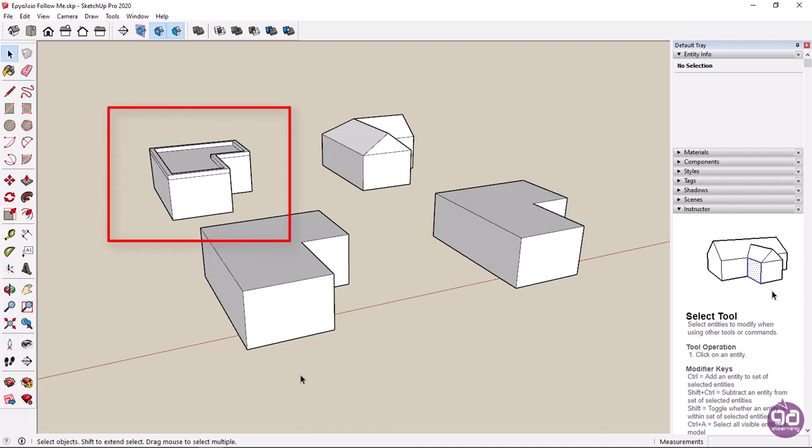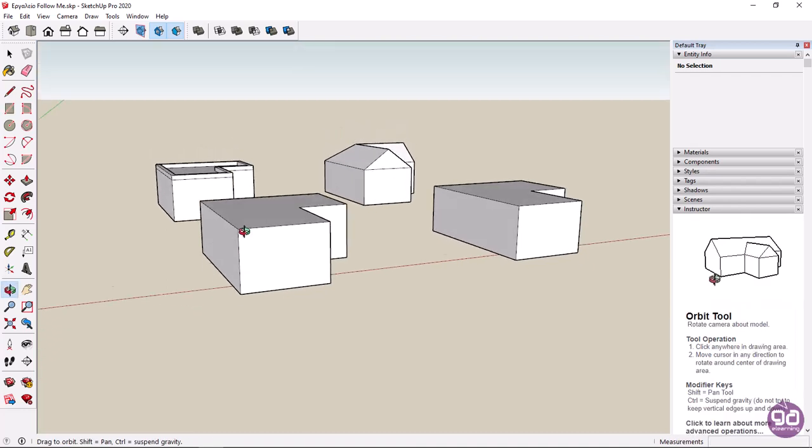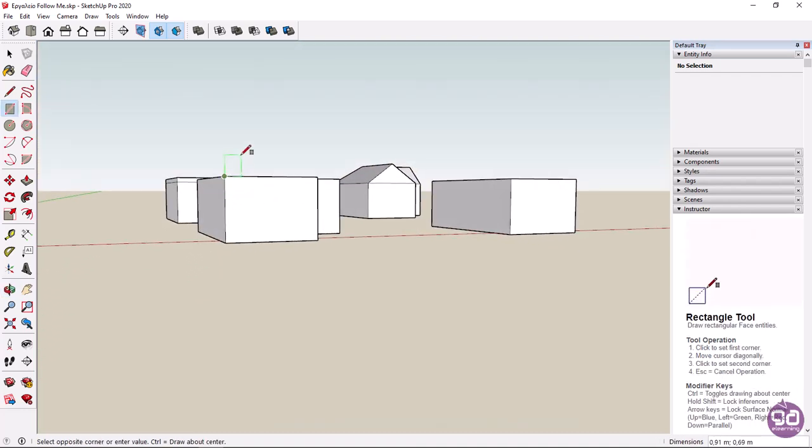In the first example, I will create a parapet on the flat roof of the building. As I mentioned, for this tool, I need a surface and a path. So, before I activate it, I have to create the surface. I will activate the Rectangle tool to create a rectangular surface. I will specify the first point of the rectangle on the upper left corner of the solid. Then I will move the cursor so that the rectangle appears green, which means that it is perpendicular to the y-axis. Now, to define its dimensions, I will type 0.3, a semicolon, 0.3, and press Enter.